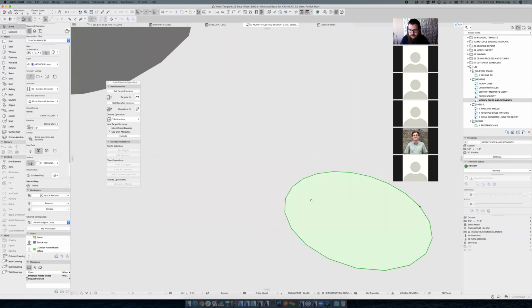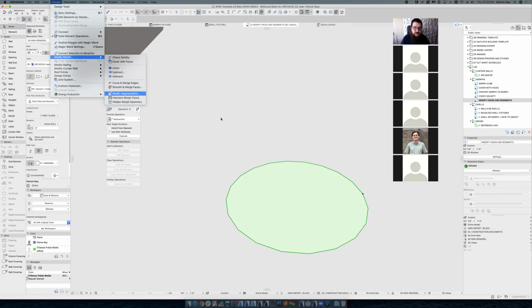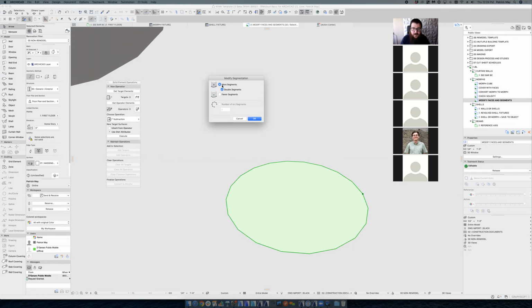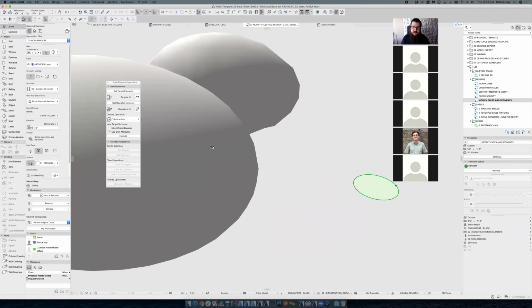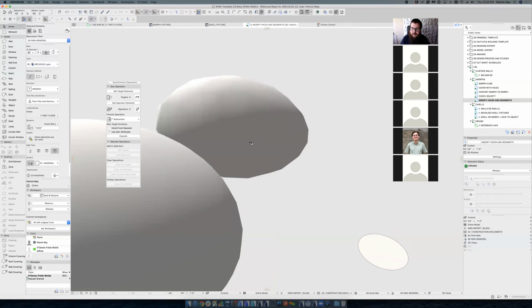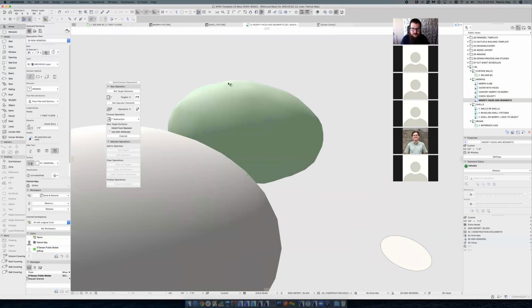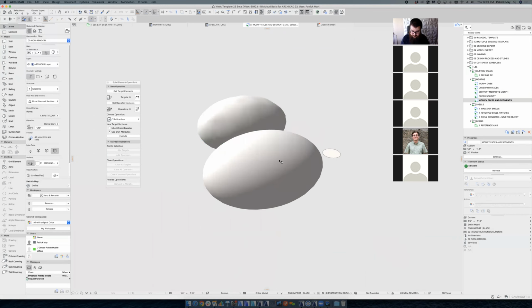This is a morph disk basically that was drawn. You can go up to design, modify morph, and this modify segmentation feature. You can add or reduce segments, and you can see how that starts to increase the resolution. It doesn't always work. In this case, this was a basic shape set to I think 5 or 6 on the resolution. If I went up to modify morph and modify segmentation, double the segmentation, it starts to smooth out, but it also just looks really lumpy, like a dinosaur egg.